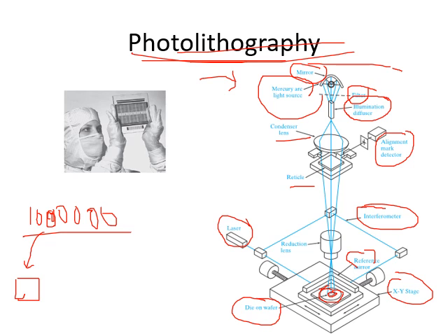I said there are two types of resist, positive resist and negative resist. In positive resist, the exposed part becomes soluble and can be removed, and in negative resist, the unexposed part or material can be removed. Silicon wafers are covered with UV light sensitive organic materials, which are called photoresist. So what is photoresist? If somebody asks you, you have to say it is UV light sensitive organic material covering silicon wafers. They are also called photo emulsion, or photoresist.